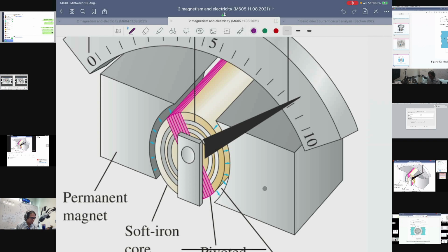That's the most favorite type of galvanometer used in that generation or even nowadays. When there is a current in the coil, the magnetic field will exert a torque on the coil, right? The torque will happen at the shaft, and it's going to deviate, or rotate, the needle from the original state, the zero position, to any bar here.